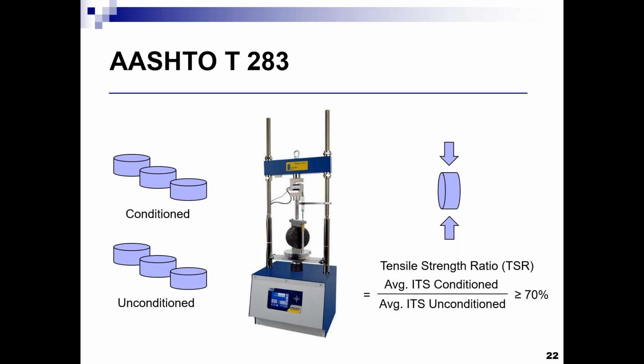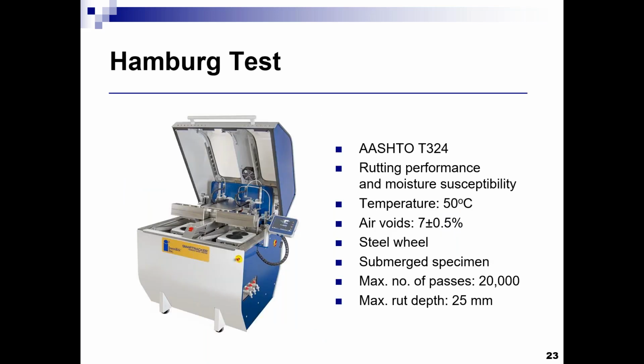Usually, mixtures that are more susceptible to moisture-induced damage are mixtures that are coarser in aggregate size, where you have more voids inside the asphalt mixture that would allow the moisture to penetrate through it. When you're dealing with a finer gradation aggregate mixture, or a mix that is richer in asphalt binder, traditionally you're not too concerned about the susceptibility of the asphalt mixture to moisture-induced damage, unless you're dealing with, for example, aggregates that have cleanliness issues, or some incompatibility with regard to adhesion between the asphalt binder and the aggregate. But other than that, usually you should be good with regard to moisture-induced damage. But we did the testing to look at the results.